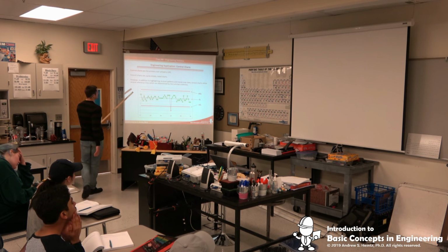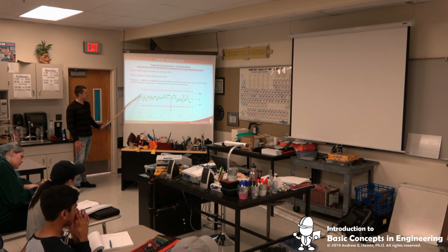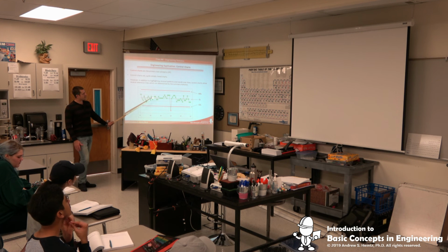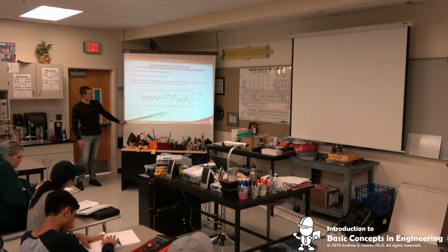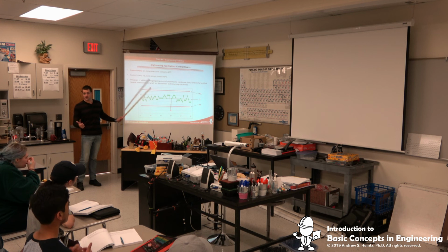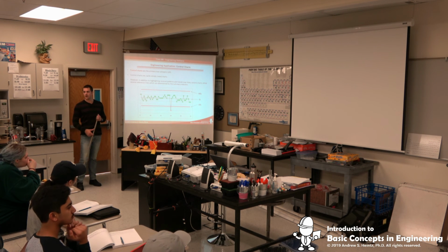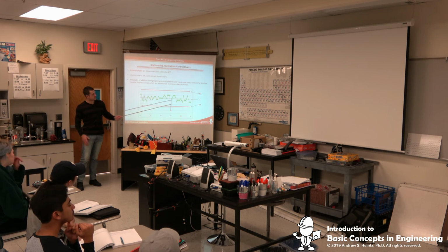Okay, so we're measuring our data, and if the point is in control, if it's behaving as it should be, it's going to be green. So we're trucking along, we're making data here, and all of a sudden we measure a point down here. This point is out of control. So what would happen here is it would log our tool. At Intel, it logs our tool down automatically and flags the engineer. The engineer goes in and figures out, is it broken? Was it just a bad measured data point? But we go in and we investigate. We stop producing product on that piece of equipment until we can get that fixed or solved. Okay? And then we bring it back up. It's running well again, and everything's okay.